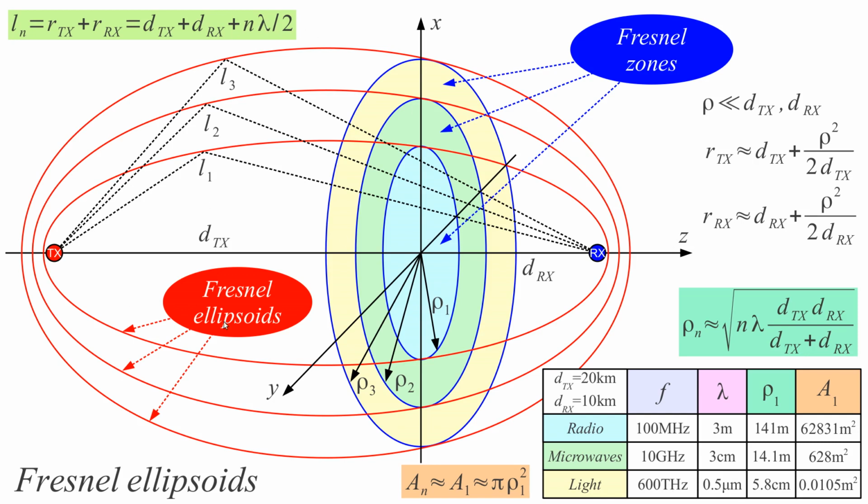This is now a little bit without proof, but we shall try to find a proof for this statement that most of the power travels in the first Fresnel zone in the next slide. This is actually the formula, simplified for the case where the Fresnel zone is much smaller than the distance from the receiver and the distance from the transmitter. Then we can simplify this equation for the radius of the Fresnel zones.